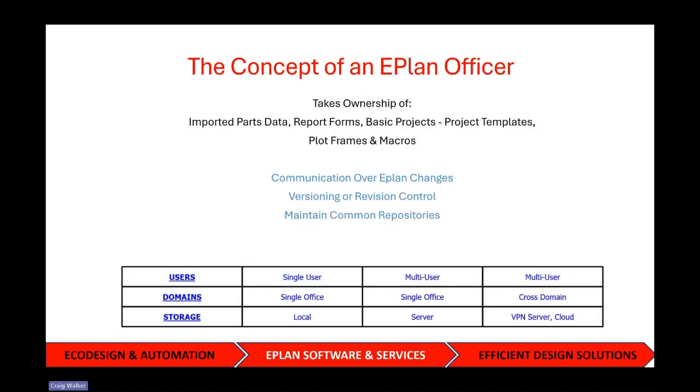So this brings us to the concept of an Eplan officer. It's a term you can replace with a different term if you want, but it's effectively someone within the company that's going to take ownership of how your Eplan is used and managing your data repositories. So this involves your imported parts data and keeping your parts databases up to date and cleanly presented, your reports and forms, having those up to date, your basic projects and project templates.